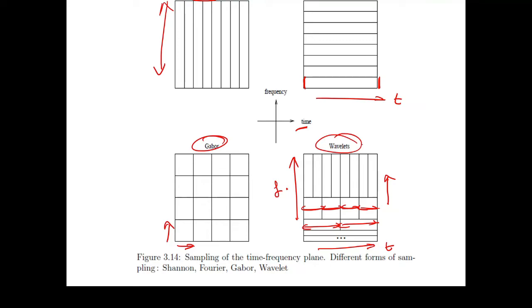So depending upon the frequency components of the signal, if you need a larger window, you will be given a larger window, and for the analysis of higher frequencies, if you need a shorter window, you will have a shorter window. This is the advantage of the wavelet transform, and this is why most of you must have heard about the wavelet transform these days.